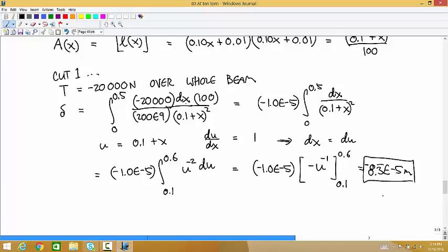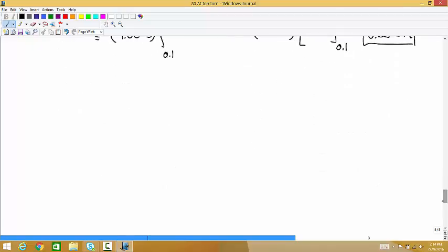I guess before I do thermal expansion, let me do one more example. I just want to show, we're used to doing cuts where the internal loads change. But when we're using these sum formulas for the total elongation, there are 4 things that go into that piecewise constant formula: the internal tension, the length, which doesn't count for this, but the Young's modulus and the area. And if any one of those things changes, you need to make that a new piece. You know what I mean?